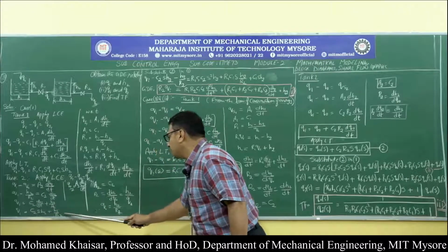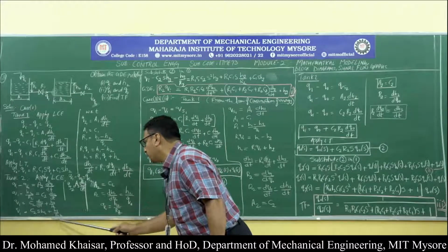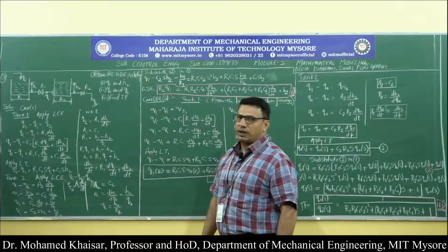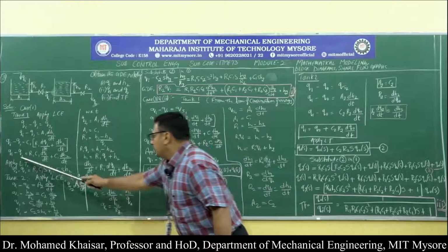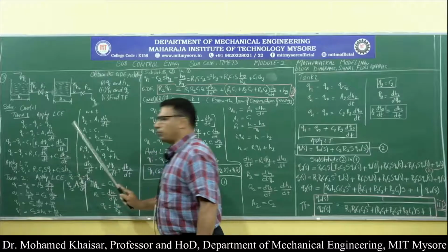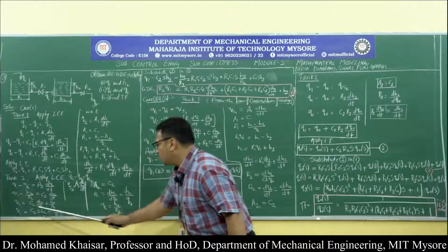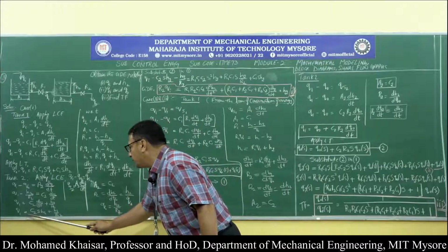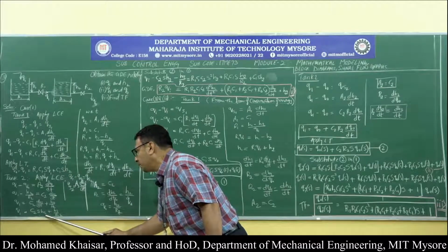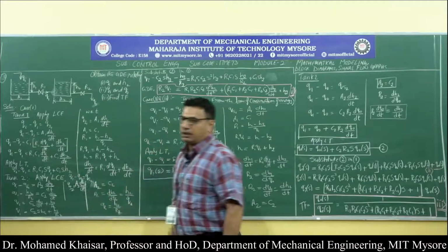Then we will just rewrite this equation, we will get Q1 is equal to C2S into H2 plus H2 by R2. Now, if you compare this equation and this equation, what can you assess? This equation is in terms of Qi, Q1 and H2, and here this equation is Q1 and H2. So, what it means to say is, you have found out the replacement for Q1. The right hand side of this equation is nothing but the replacing term for Q1 in this particular equation.